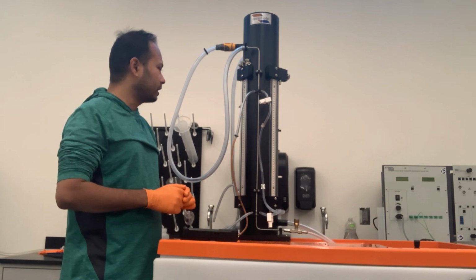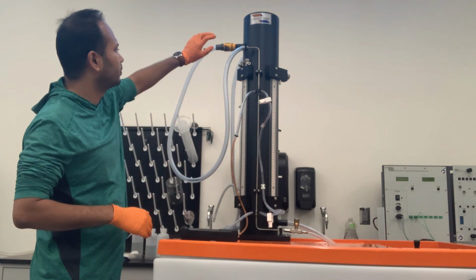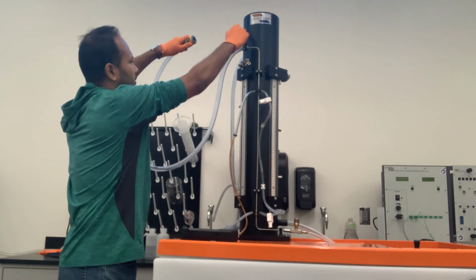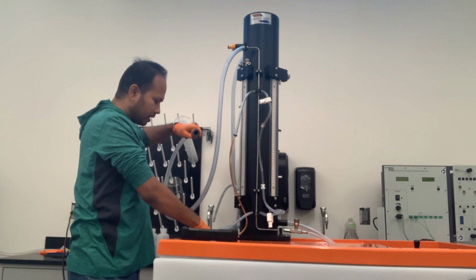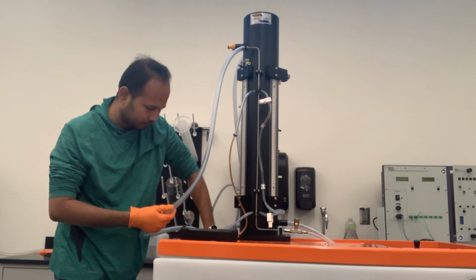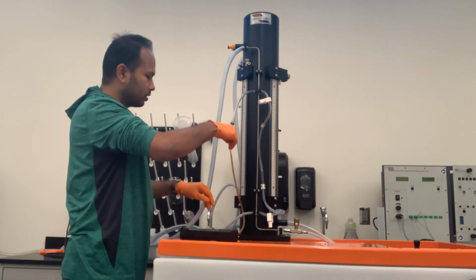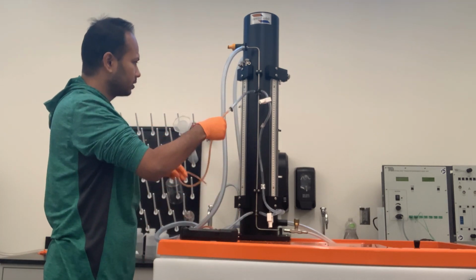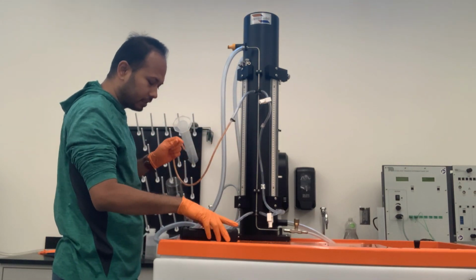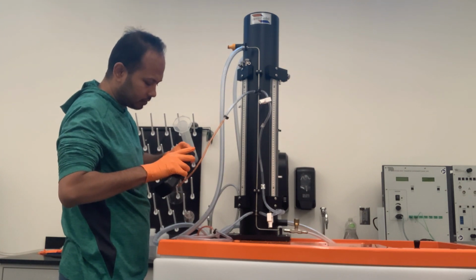So to perform the test, first we're going to run the high flow rate test. For that, we have to take the inlet of our pipe and directly connect to the outlet of the pump. And these are the manometer outlets. So this is the first point. I'm going to connect it to our digital manometer.